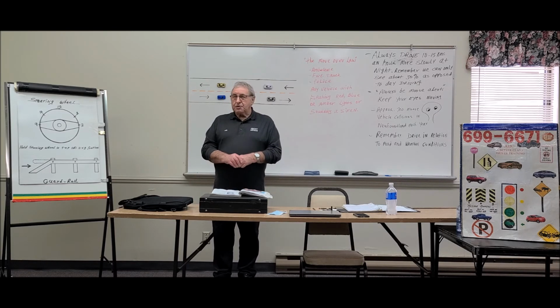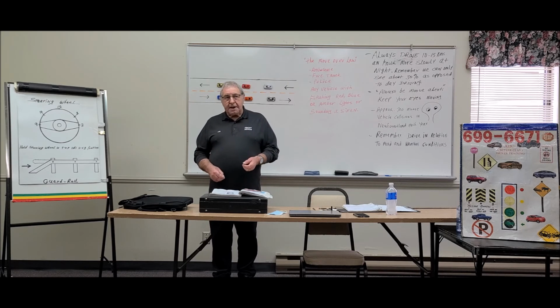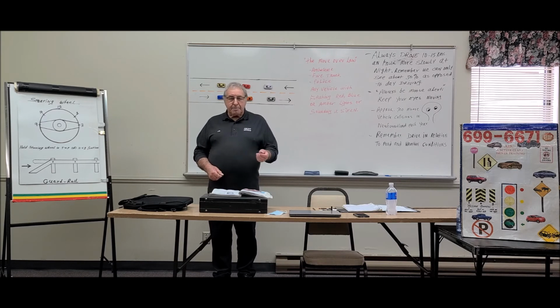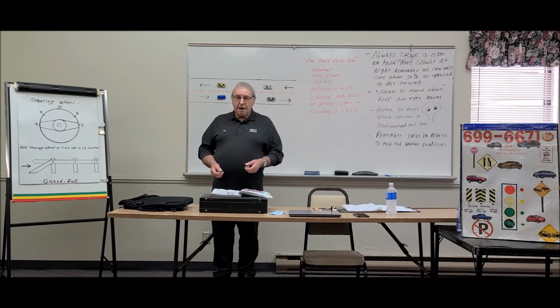A lot of people ruined their transmissions then, because with older cars, once you took it out of drive and put it in 2 or 1, when they got up the hill, they forgot to change. It couldn't get back out anymore. And at 5,000 or 6,000 kilometers, their transmission was ruined.